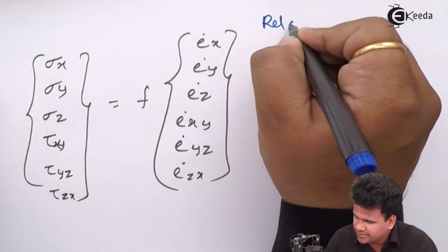The left hand side of the equation, that is equals to, let us differentiate this inside. So body force per unit volume will write down later. So this is differentiated inside, so that will give us minus of ∂p/∂x plus 2μ into ∂²u/∂x² minus 2/3 into μ, and this will be differentiated inside.